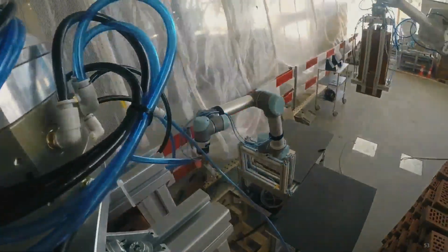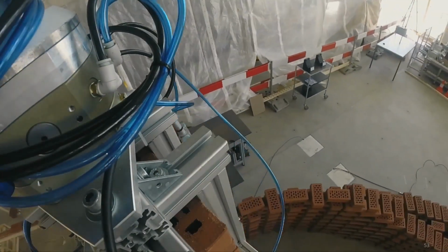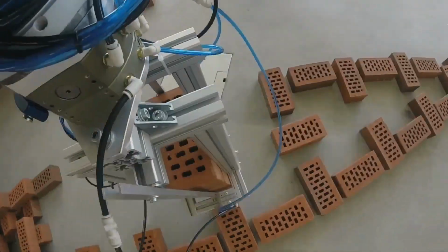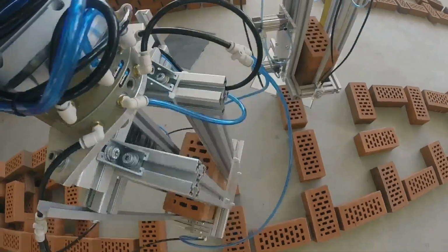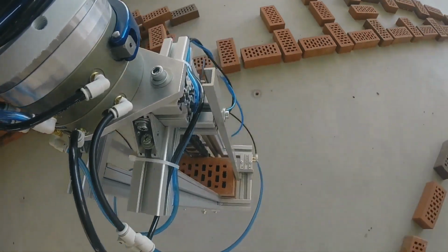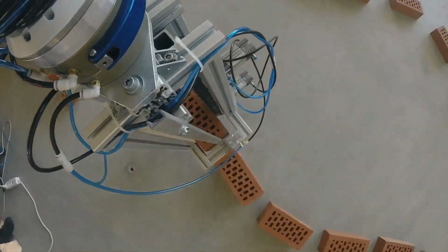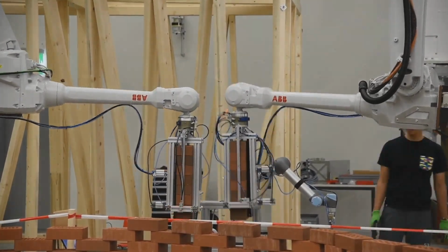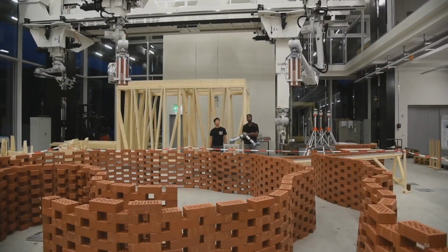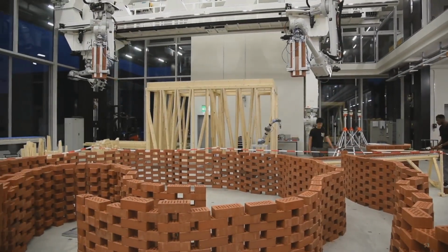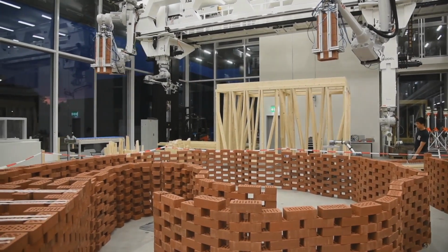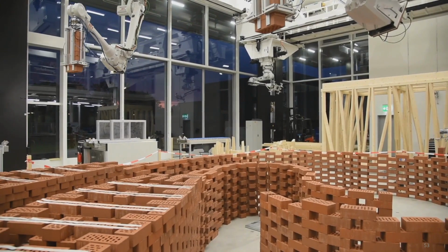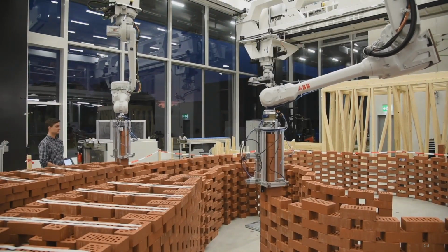In addition, the robots had to be synchronized time-wise so that one doesn't get a lot faster than the other one, and we had to make sure that the sequence actually avoids any types of collisions. So dividing the geometry of the labyrinth in a sequence that ensures that there are no collisions between the robots and that all bricks can be reached, that they can be approached from a direction where there are no other bricks in the way. That was one main part of the process.